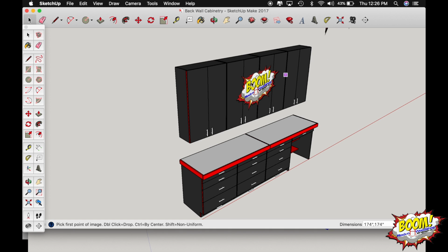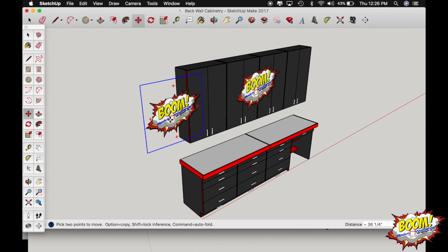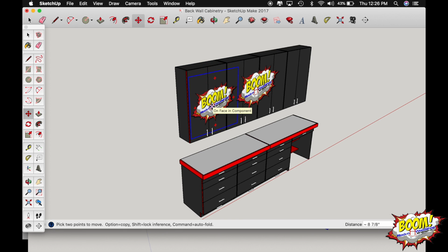And it will bring it in like this. Before you click on where you want it to be, you need to find the plane that you want it to be on, and just click on that plane. And then it will ask you to resize it after you've clicked. And then you can just bring the size into perspective and then move it wherever you want. So that's pretty easy to do. Okay, so that's how to bring in an image that you've already made, a PNG file image too. So there's another bonus lesson.